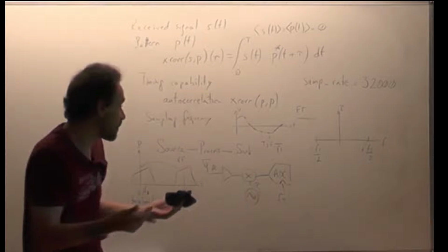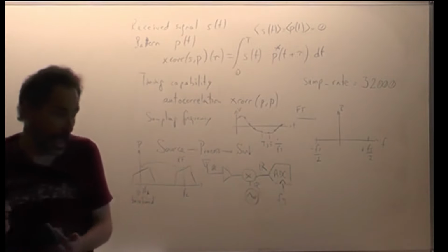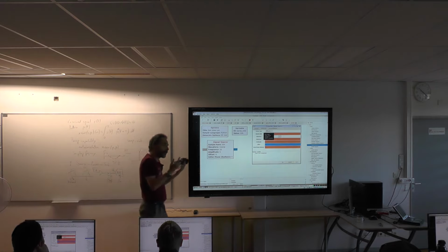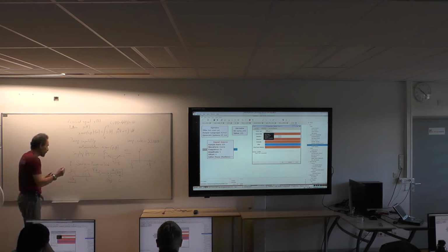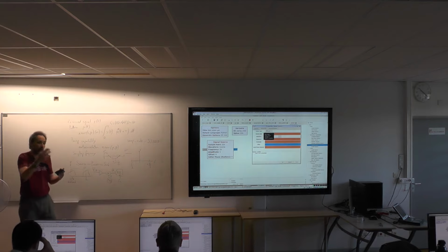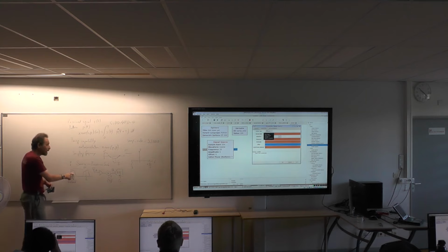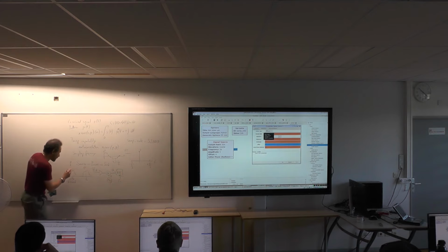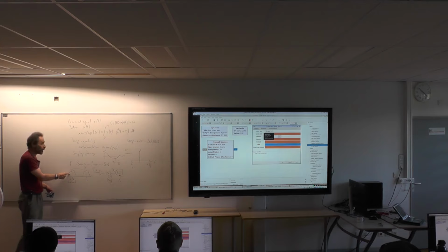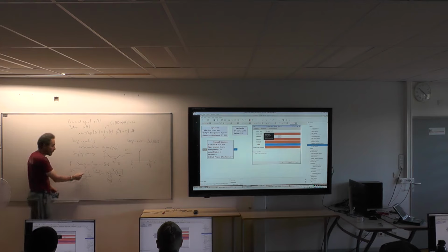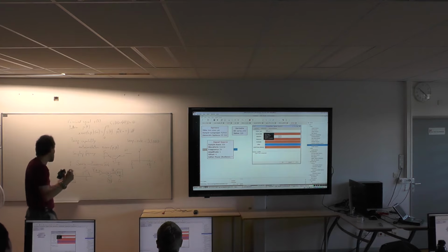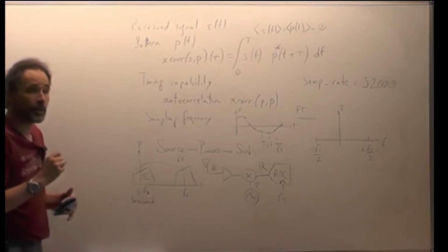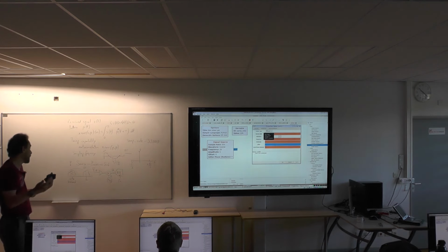Now, if you do this, you start with a real voltage, you multiply with a real oscillator. When you multiply two real quantities, you end up with a real quantity, which you sample. And what is the characteristic of the spectrum of a real quantity? The spectrum of a real quantity is an even function. The negative component is the complex conjugate of the positive, so the magnitude of the negative spectral component is the same as the magnitude of the positive spectral component. So if you just do this, you're going to end up with an even spectrum, and we lost half of the information, because no one said that the spectral components below the radio frequency carrier must be the same as the one above. So we need to find a trick to recover the negative part of the spectrum, and if you have a non-even spectrum at baseband, it necessarily means that you must have a complex quantity. The only way to have a non-even spectrum at baseband is because you have complex information.